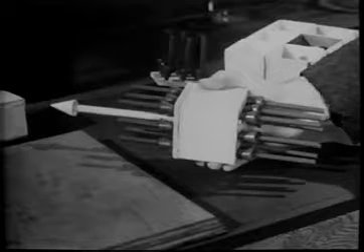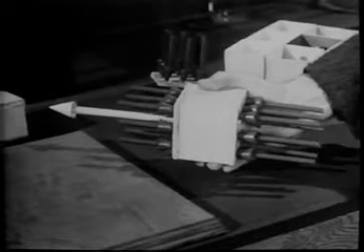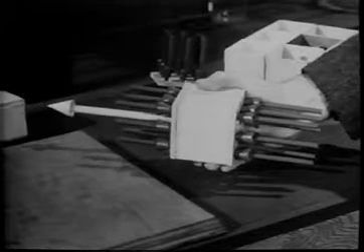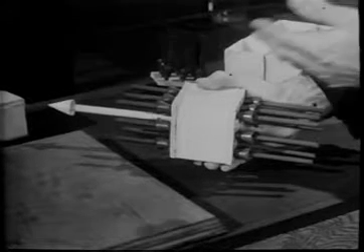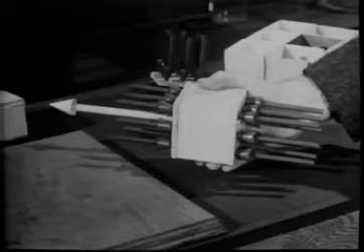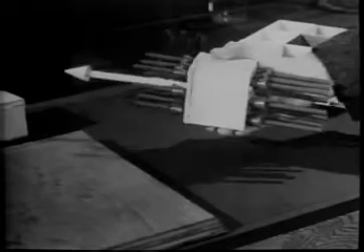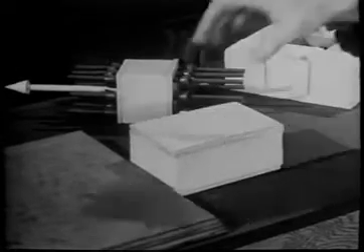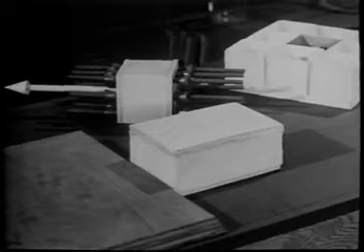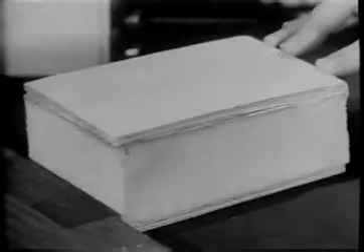So far, we have considered only stresses normal to the surfaces of the fluid particle. Moreover, we have thought of the fluid particle as being rigid, like this block, so that it could be displaced and turned, but not deformed. Actually, fluid particles can and do undergo great changes in shape, even more easily than this block of foam rubber.